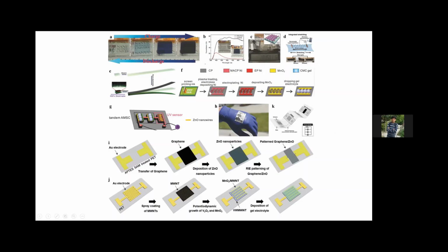They get the film deposited, supercapacitor material deposited onto it, and then next they deposit the current collector or the other material first. Suppose in this case, first in the pattern they deposit the current collector, and then they deposit the metal oxide, and then they put the electrolyte.